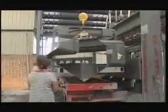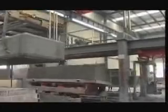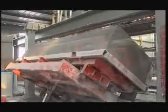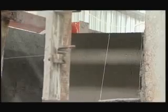For the ground turnover cutting, the cake is lifted onto the tilting table by hoist, when the hardness of the cake is ready for cutting. After being demolded, the cake turns by 90 degrees, and moves to the direction of cutting center, at an upright position. Firstly, the horizontal cutting machine moves into place, and cuts the cake horizontally. And it peels off the skin of the cake in 4 sides.